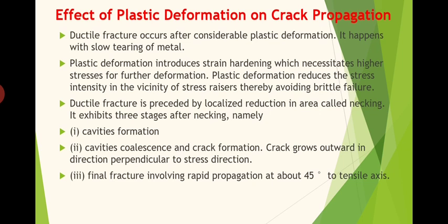But I have already told, since plastic deformation is taking place in the case of ductile material, there will always be shear stress acting along with the normal stress. So more or less, if the stress exceeds the yield stress, the dominant phenomenon leading to the crack will be the shear stress also. So shear stress also has some importance. Because of the effect of both normal stress as well as shear stress, the cracking is taking place. So always after a particular limit, the crack propagation will be affected by the shear stress also.